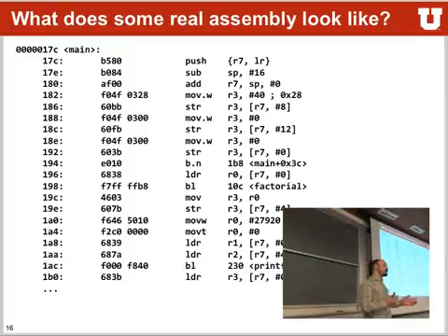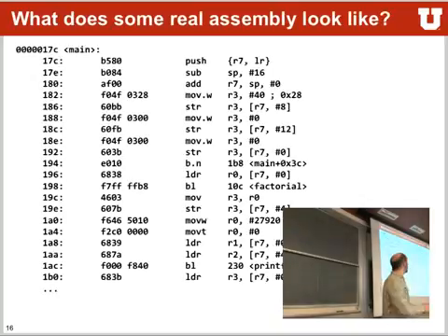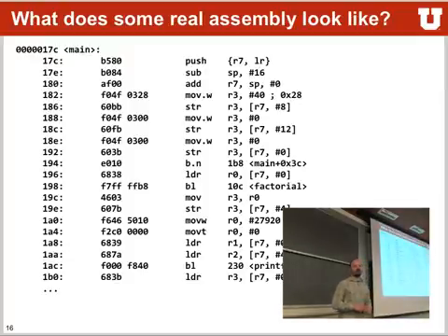Remember when I talked about that the ISA can help the binary interface and function calls? This is one of these things that we will see in certain branch instructions. The microcontroller does actually a couple of pushes and pops for you, just automatically by executing a certain assembly instruction. This .n and .w that you can see sometimes here, so a .w and a .n down here, just helps the assembler to tell, I really want a 16-bit instruction, or I really want this to be encoded in a 32-bit instruction. That's all it does.